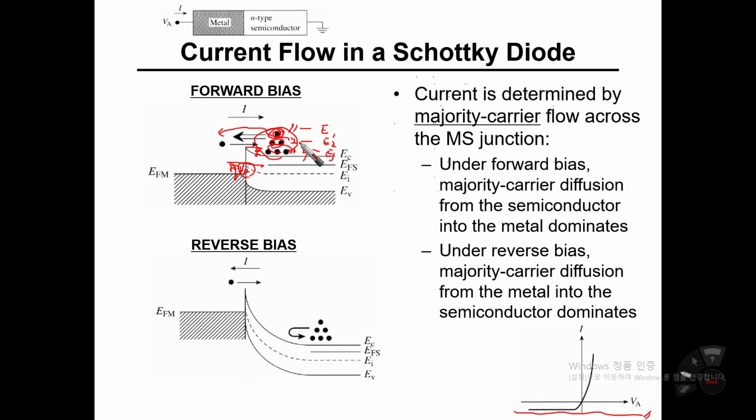Why is that? Because of the density of states and the Fermi function. So everything we have learned, and why the electron distribution in the conduction band is significant and important in describing the current flow in a Schottky diode. You now get the concept and the physical origin of why the diode can flow current at an exponential pace when the voltage across the Schottky diode increases linearly.